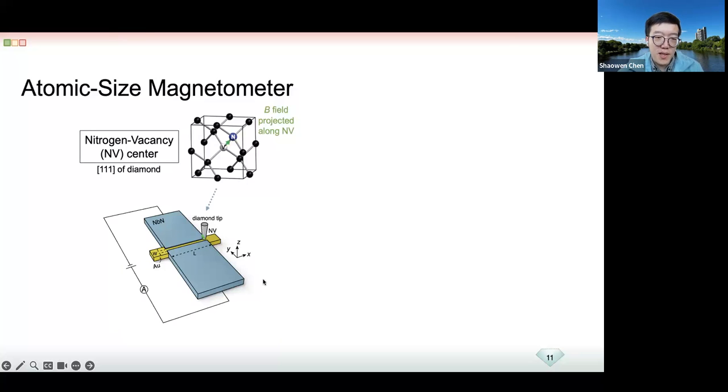and try to measure our planar Josephson junction. The planar Josephson junction we have in this case is a superconducting-normal-superconducting junction, and the superconducting material is just niobium, and the normal part is just gold. So it's actually a very, very simple SNS junction. And here are some of the parameters of the junction.